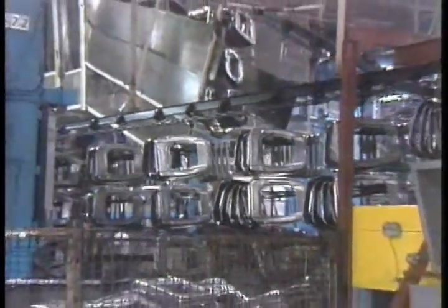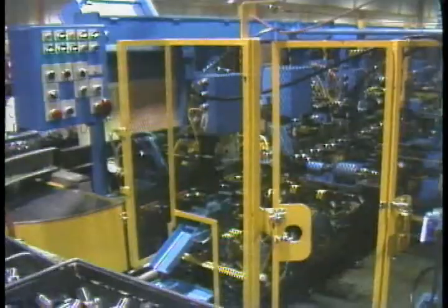The load a motor is driving may rotate, like a fan blade or pump impeller used to move air or a fluid, or the load may move in a straight line, like a conveyor belt, or the mechanism which moves the cutting head on a milling machine. But however the load moves, a motor's shaft rotates. So the force it exerts is always a twisting or turning force called torque. A straight line force, or an ordinary push and pull, can be measured in pounds or newtons. But torque is measured differently.